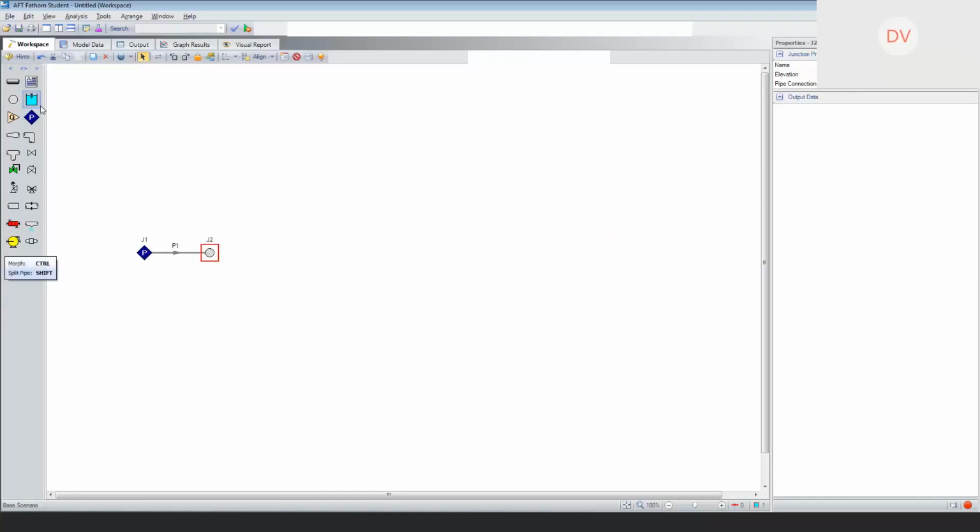So I'm going to go through the process of just building each of these segments, and like I said, I like to show it as the elevation profile shows, and it helps me visualize what's going on. And it does not have to be perfect by any means, because it's just a representation of your pipe, and the most important part is just to have the pipe segments in there, your pressure input, your pressure output.